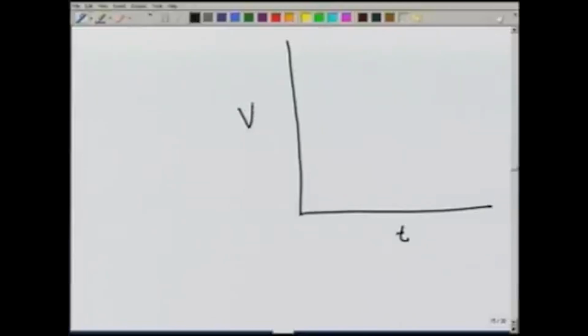So, if we draw the mass curve, which as we have seen would look like this, during periods of high discharge, the slope will be larger, then as the discharge reduces, the slope becomes flatter, and then if another storm comes, it will go up. Now, we are discussing this on a very short time basis, maybe a few weeks or a few days, but generally this analysis is done for the annual flows.